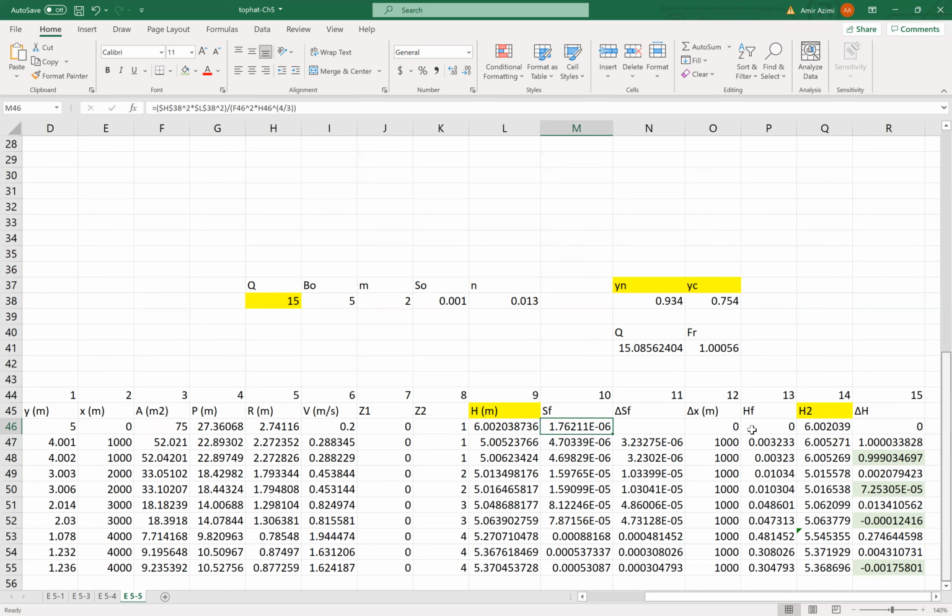And then we calculate head loss, which is distance multiplied by friction slope, and then the energy at the upstream, in this case, is the energy minus the energy loss. Then we have delta H, the difference between the energy and the energy that we calculate by estimation of head loss. And the difference should be 0.